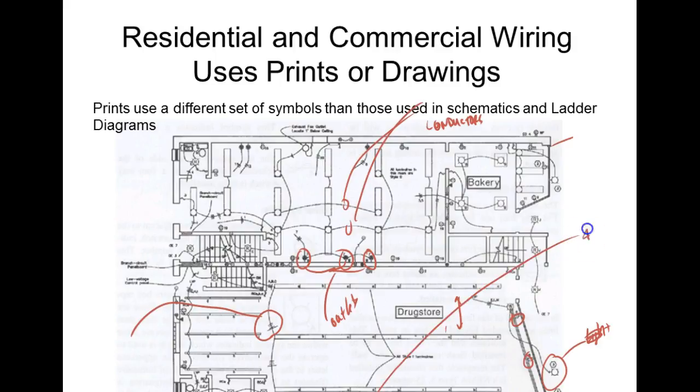And if you can see, it's got a little 4 on it. What does the 4 mean? Anybody know? Nobody's here at commercial wiring. Well, if you look in your panel box, what most people call a breaker box, every breaker's got a what? A number. Well, that tells you what circuit those wall outlets hook up to. So the electrician who would run this would know which breaker in the panel box to connect them to. Breaker number 4.